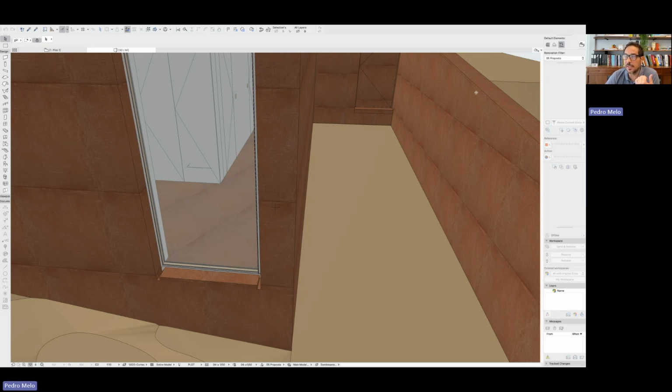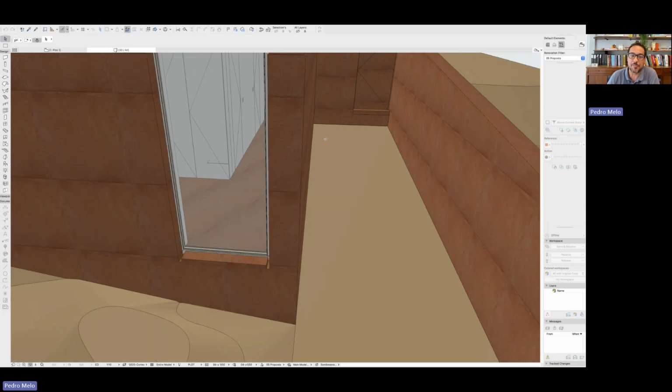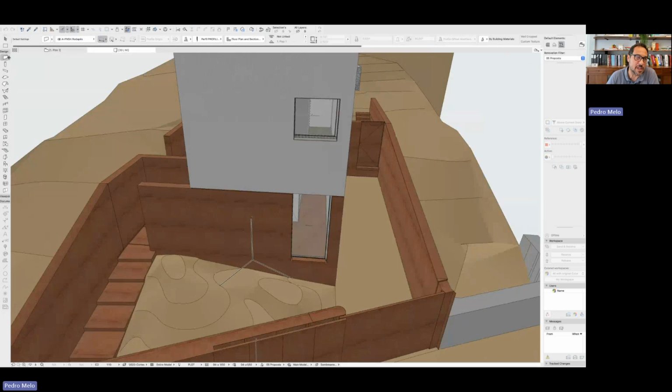So with our template, we do a lot of renovation. We have views for everything. When you start doing something, you have all the views that you need for every scale. We'll talk about it. I know that there are several different strategies for doing things. We do it by scale. We don't do it by stage, because there are projects where we submit and then we use different scales. For example, a very big project detail-wise would be 1 to 50, but some projects are so big that we have 1 to 100 and 1 to 50. So for us it makes more sense to do it by scale. But we have hundreds of favorites, and I would stress this, but we'll go on to it. And this is producing all the documentation almost automatically. So everything is here.